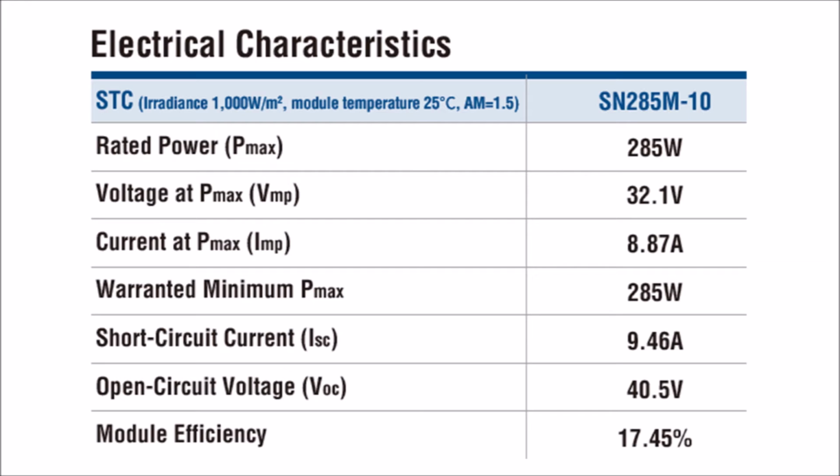The maximum voltage and amperage are used in system design rather than the operating voltage or amperage. A solar array may be designed for 600 volts, but it'll operate at a lower voltage.